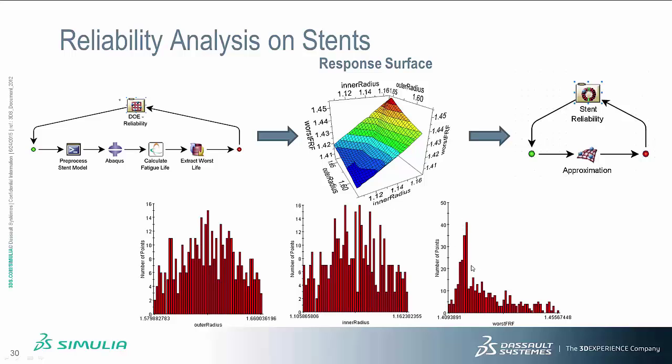Most of those fatigue factors are in the range of 1.41 to 1.42. That means for most of the changes in the radii, the worst fatigue factor does not change. So the optimized stent geometry that we have come up with is very reliable for certain changes in the artery dimension. That means it's suitable for different subject-to-subject variation in the population for the artery size.